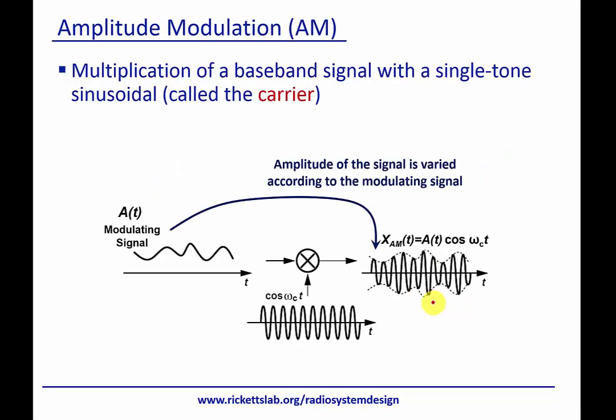So let's talk about basic AM modulation. And the idea is we've got some signal in the time domain and we're going to multiply it by a carrier, and it's pretty intuitive just to see this is the waveform that you get out. So from the time domain, this is pretty intuitive, but as we talked about in the previous module, going from the time to the frequency involves a little bit of understanding the Fourier transform and what happens when we do this multiplication in the time domain.